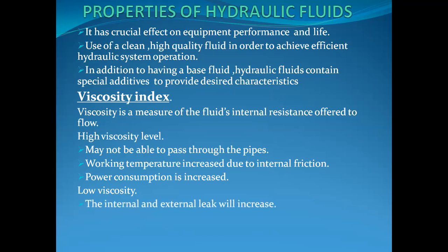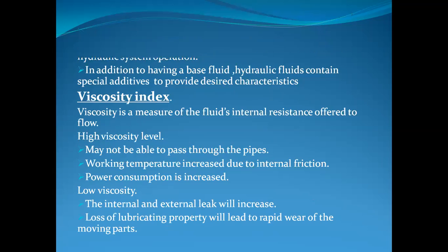The internal and external leaks will increase. This may be hazardous to the system and to the people working around the environment, and loss of lubricating property will lead to rapid wear of the moving parts.